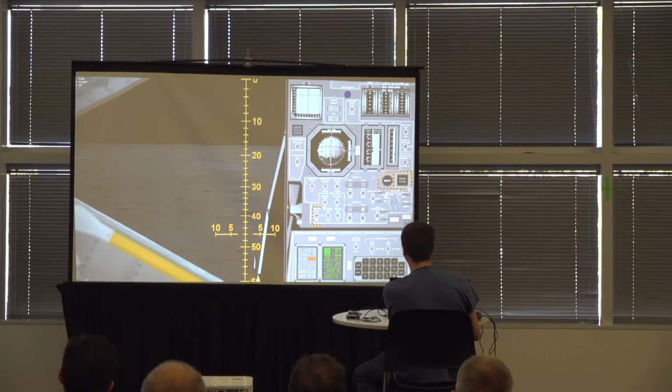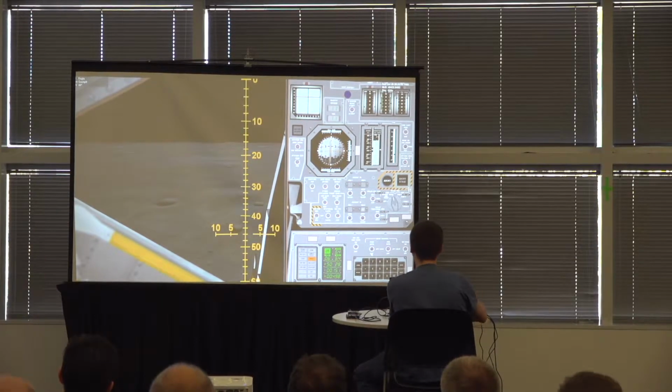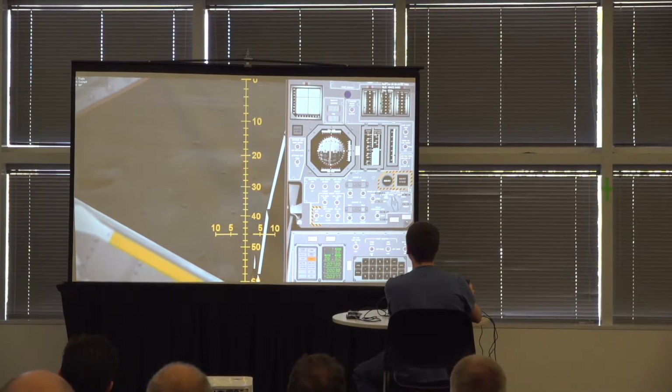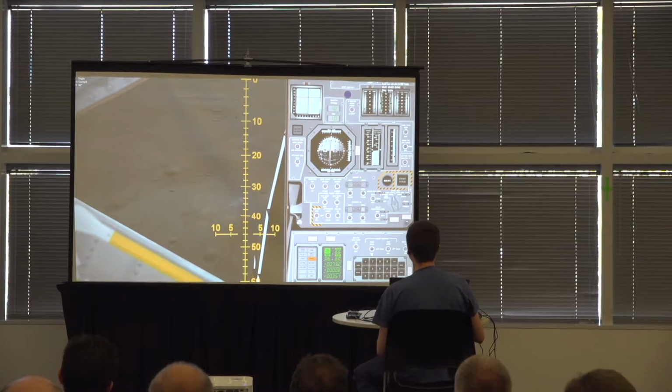When we get to about 500 feet, I'm going to do what Neil Armstrong did and switch into manual mode to divert away from this boulder field that we're going into. To do that, I'm going to switch into attitude hold, push forward, and click my rate of descent switches up to null my descent rate. Okay, so we are now in a hover.